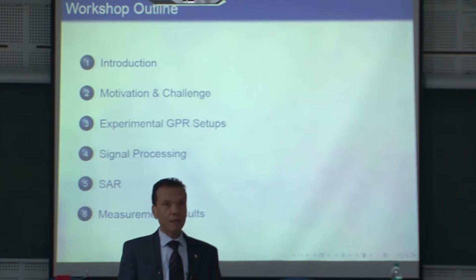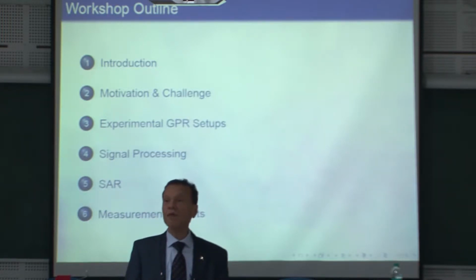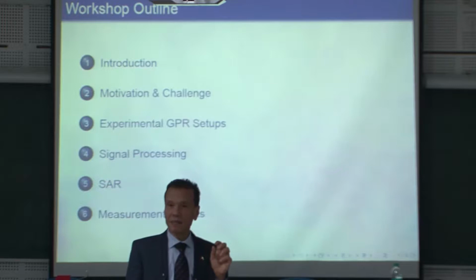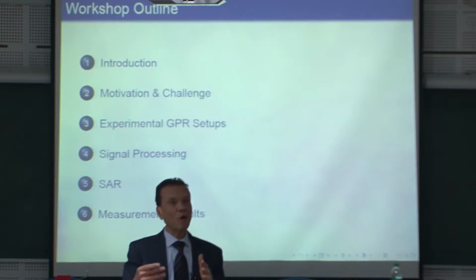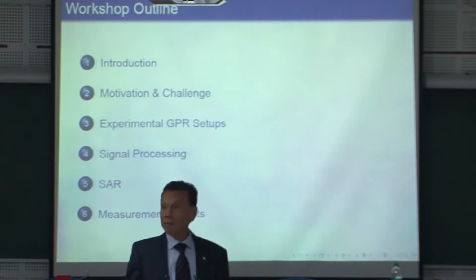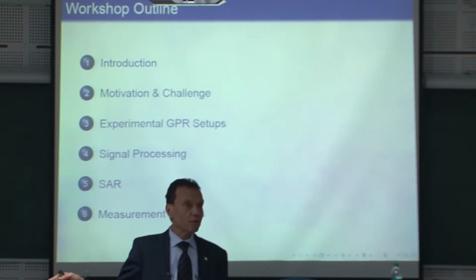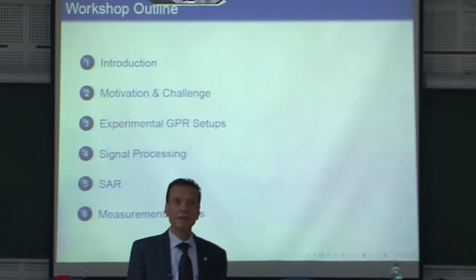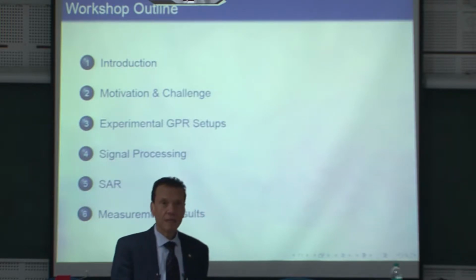Okay? In other words, if you have a continuous antenna like a dish, this is now the entire aperture, radiating or receiving. If you sample so that you have point sources or point antennas, this also explains why the antenna pattern of an array repeats itself. You have it also in digital signal processing. You always have periodic phenomena or periodic behavior.